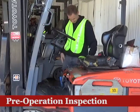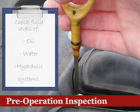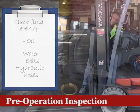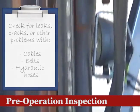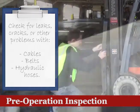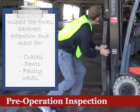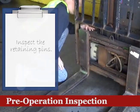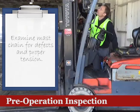For the pre-operation inspection, start with checking the fluid levels. Make sure there is a proper amount of oil, water, and hydraulic fluid. Check for leaks, cracks, or other problems with cables, belts, and hydraulic hoses. Inspect the forks, backrest extension, and mast, for cracks, dents, or faulty welds. Make sure the retaining pins are in good condition. Examine the mast chain for defects and proper tension.